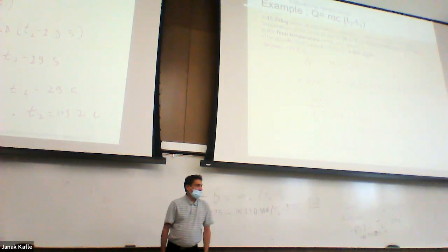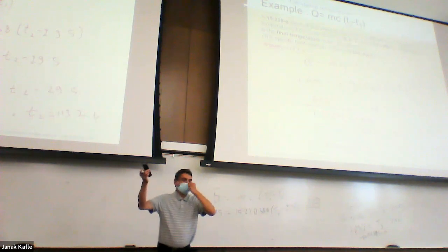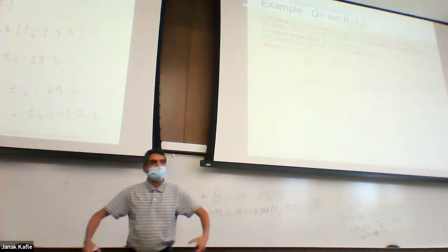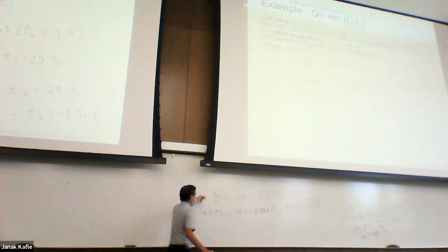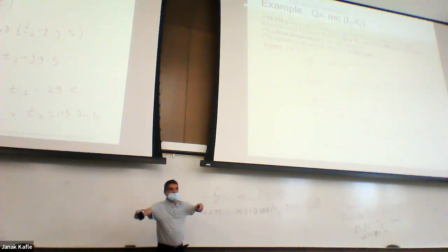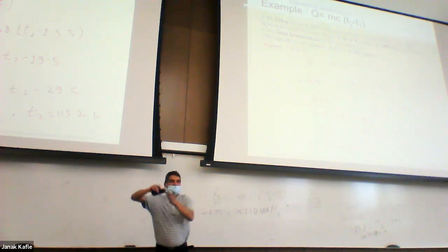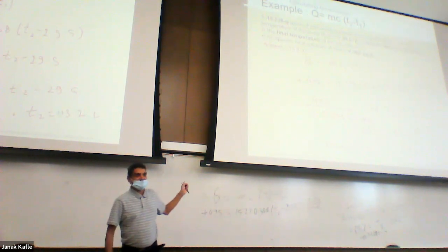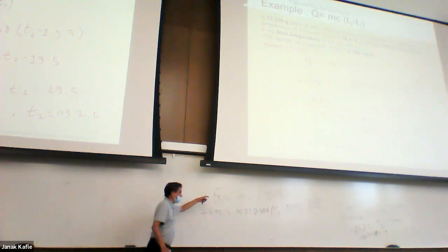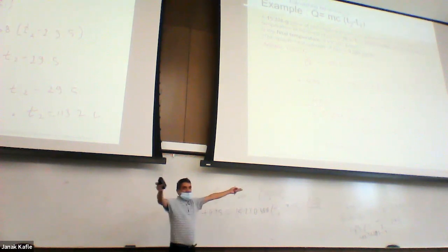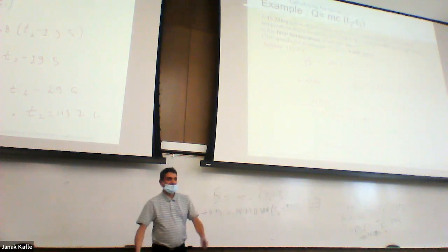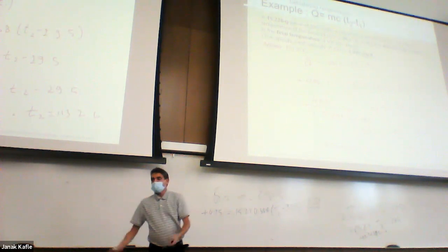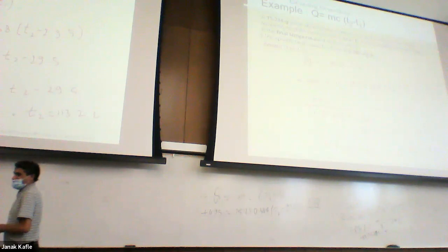Good. I read the book, and some people put plus here all the time, and when they give the conclusion later they say, oh, since it was getting heat, I am going to adjust something like that. But when we start practicing in the beginning, we must write minus or plus here. If something is losing, write minus. If something is gaining, write plus. And while we calculate temperature, you will never make a mistake. Everybody got that? Good. All right, so we'll continue.